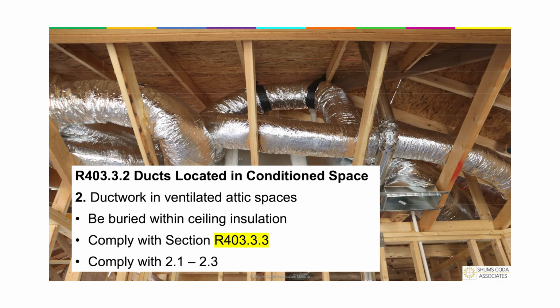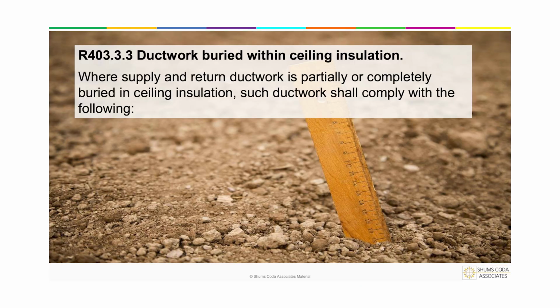Now, we're going to take a look at what 403.3.3 actually tells us. So when your supply and your return ductwork is completely, or, and this is the incredibly important part, I want you all to remember this, or is partially buried inside the ceiling insulation, it's got to comply with all of this to be considered as part of conditioned space.